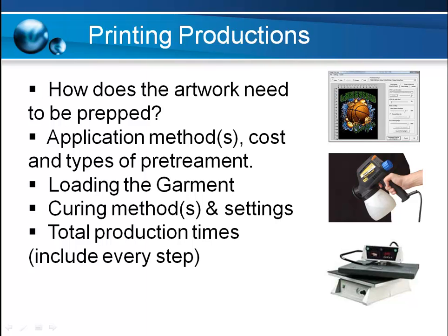It's important to understand that the distance from the bottom of the print head to the top of the substrate needs to be at a specific height, or a very small window of height. That way you get the best or optimal looking print. So in some cases, some printers require the use of hoop rings or clamps to make the garment sit really flat. Other printers have a larger gap depending on the type of print head being used, so it makes it easier to print over seams, buttons, zippers, and other items.